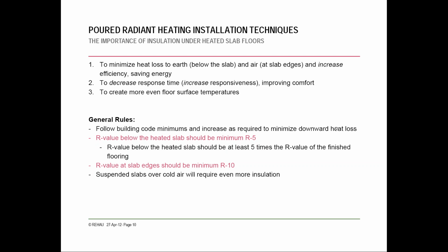Some of the tarp type insulations, CoverTech for example, that have a foil layer, tend to have a slightly lower R value, but because they have an aluminum reflective layer, they're directing the radiant heat in a different way. So it's not necessarily apples to apples. You can get a great tarp product and have a similar improvement as a standard rigid foam.